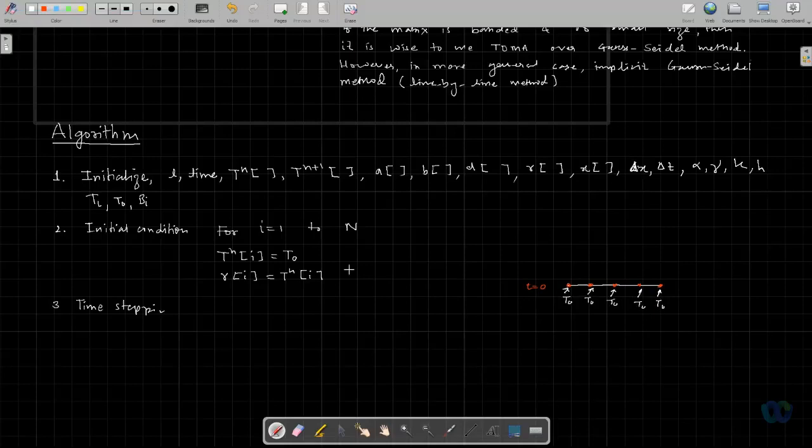By doing this, we have done the initialization. Now, by time stepping, we move into time, so that we go for the next time and calculate here. Now this is a boundary node, and this is a boundary node, so these values will have to be forced by you, and the interior will be calculated.